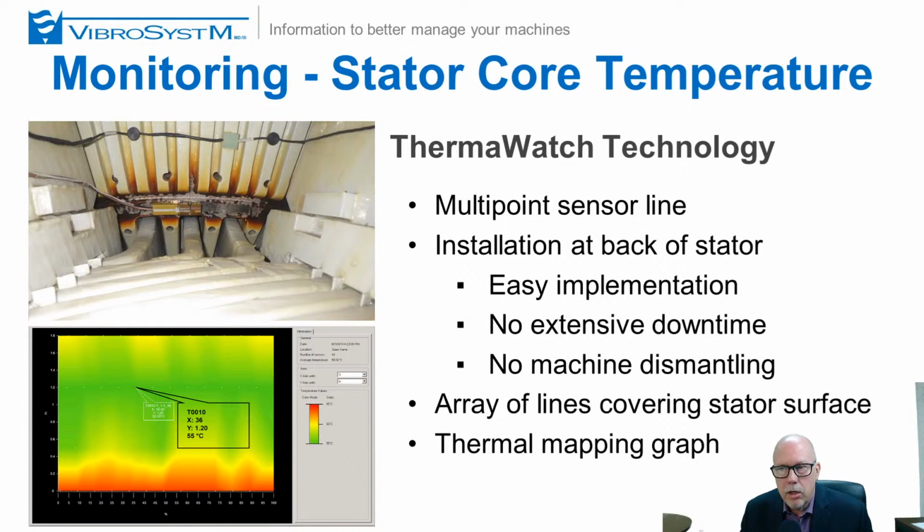Okay, and also the same technology can be used to monitor the core. In some cases, there's the picture you have here. This is an existing customer of ours that's having excessive problems with stator core temperature, and that compressing plate is also getting very, very hot to a point where it's cracking. So we're helping this customer understand exactly why this is occurring. How bad is it when it's in operation? Are there any operating conditions that create more temperature than others, to try to avoid those?